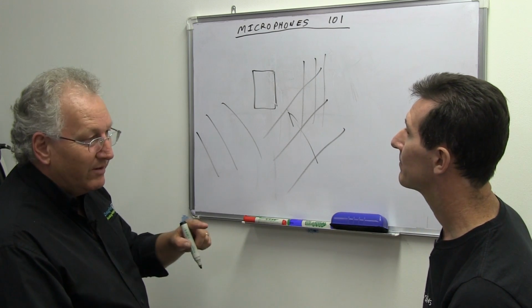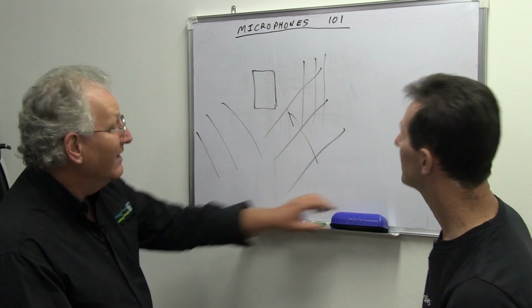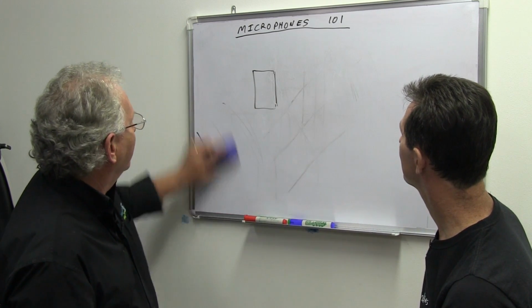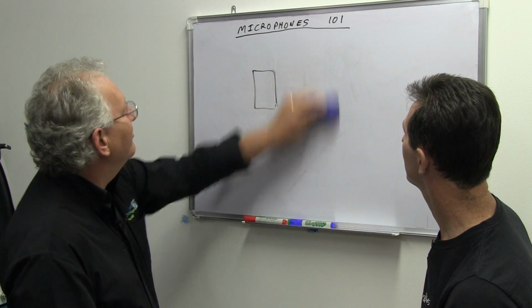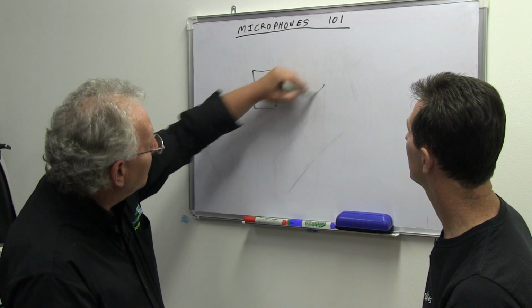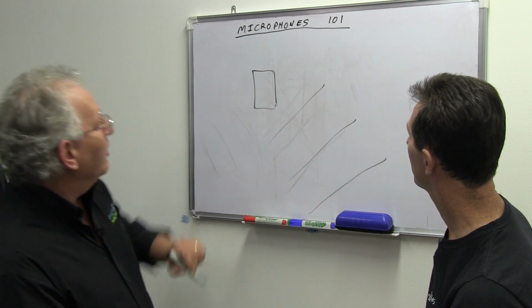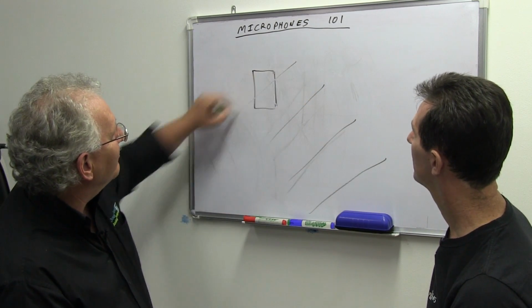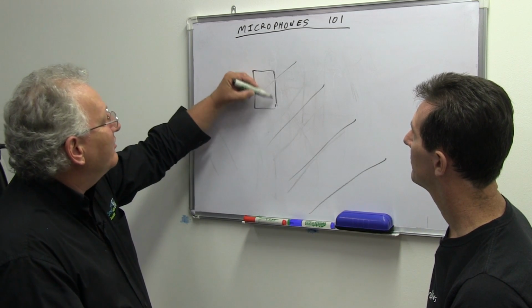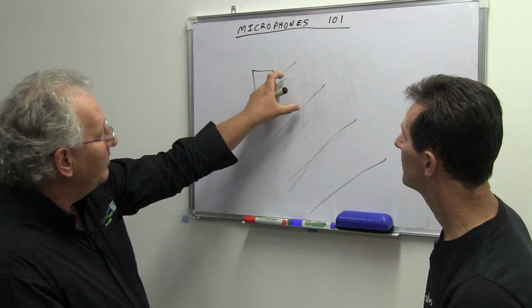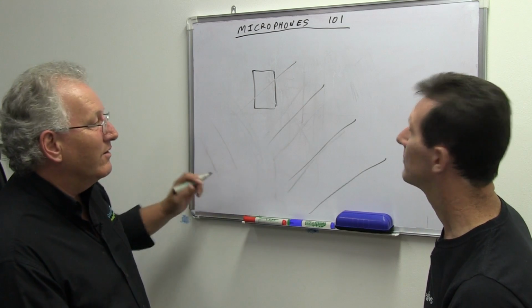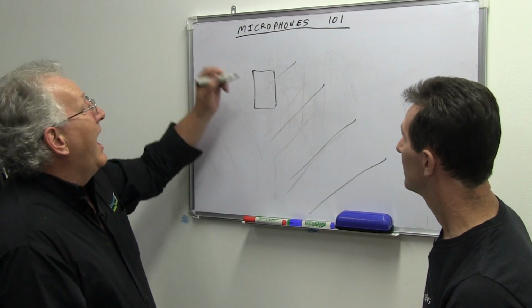There is, of course, a caveat, and that's simple frequency dependency. If the wavelength coming across that is fairly long, and the size of the diaphragm is small compared to a wavelength, then it really doesn't matter what direction the waves are coming from, it's going to receive.